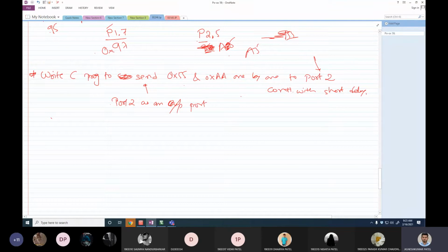That's the important information. You have to let the 8051 know you want to do something with port 2. So how to do that? We know that port 2 is a whole thing, so I'm going to use it with SFR P2 is equal to 0x. Which number? Anyone can answer. A0. Okay, correct. A0 is the number. So I'm going to write SFR P2 is equal to 0xA0.